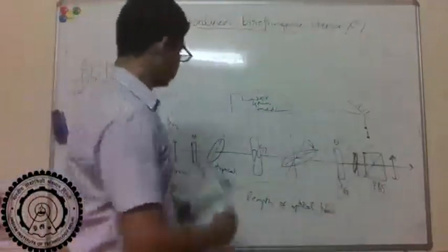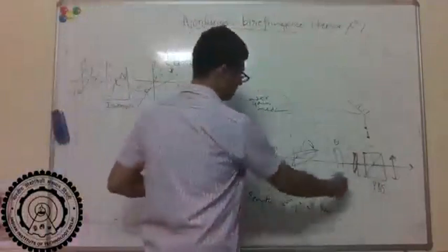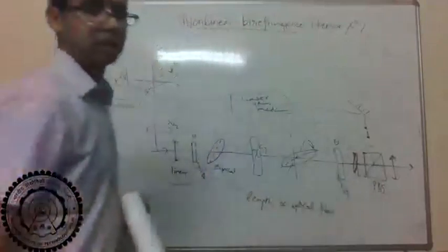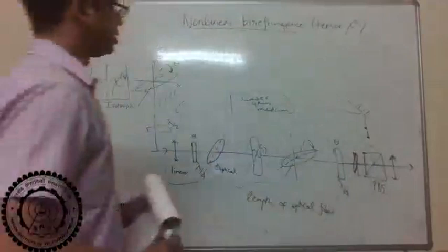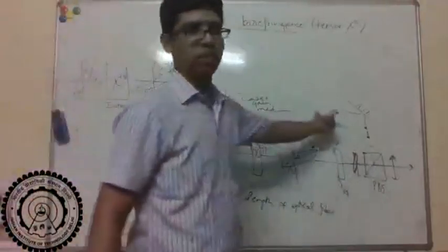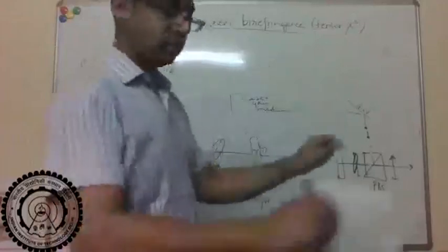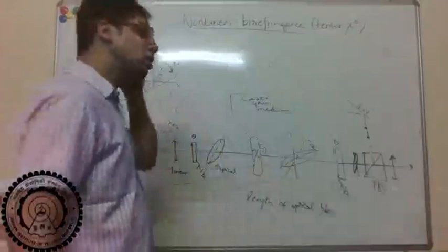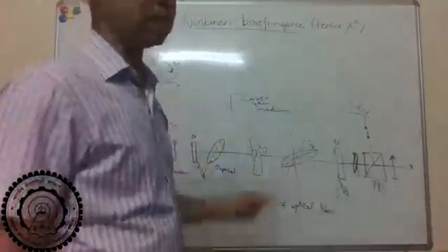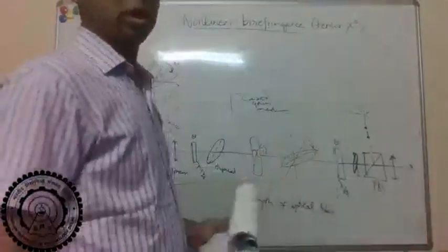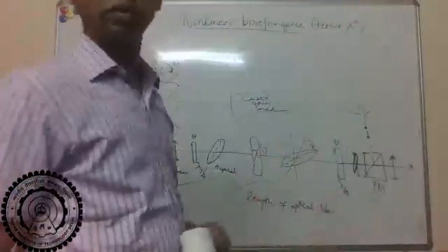So, at least the nonlinear medium, easily you can just replace by an optical fiber. And so, for example, there are fiber lasers where everything is a fiber. So this gain medium is also some erbium doped fiber or something. Right? So everything is just fiber components integrated, and you get a mode locked laser out. So pulses, ultrashort pulses. Okay.